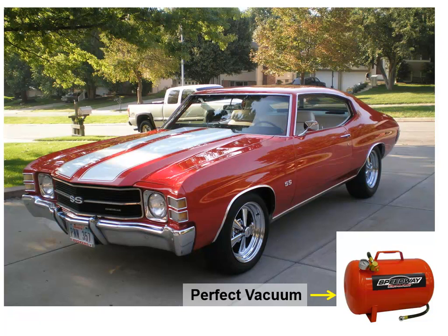Now, let's say that you had a perfect vacuum inside of a tank like this, that it had been completely evacuated of any air. There weren't any gas molecules at all inside of that tank. Well, if that was the case and this tank was in the Earth's atmosphere, then the Earth's atmosphere would be pressing on the tank with 1 atmosphere. There would be nothing inside, and so it would have gauge pressure of 0 inside of the tank.